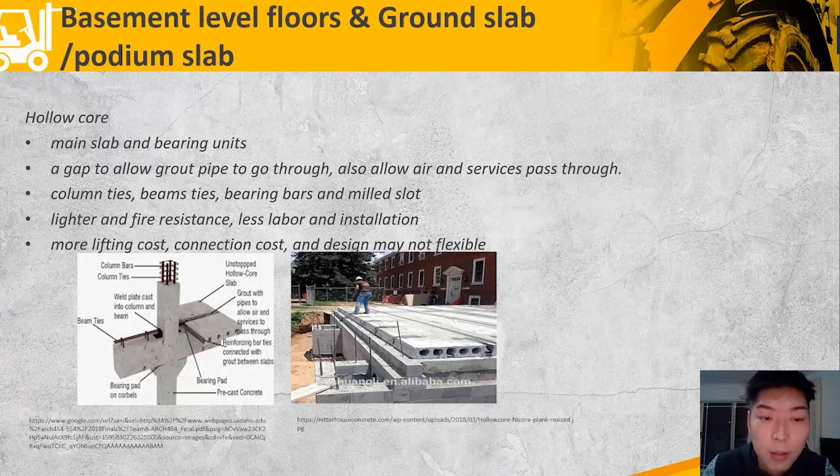It is lighter and fire resistant. It is more convenient to install the services such as electricity services. It requires less labor and installation process. However, hollow core slab needs more lifting cost, connection cost, and the design may not be flexible.